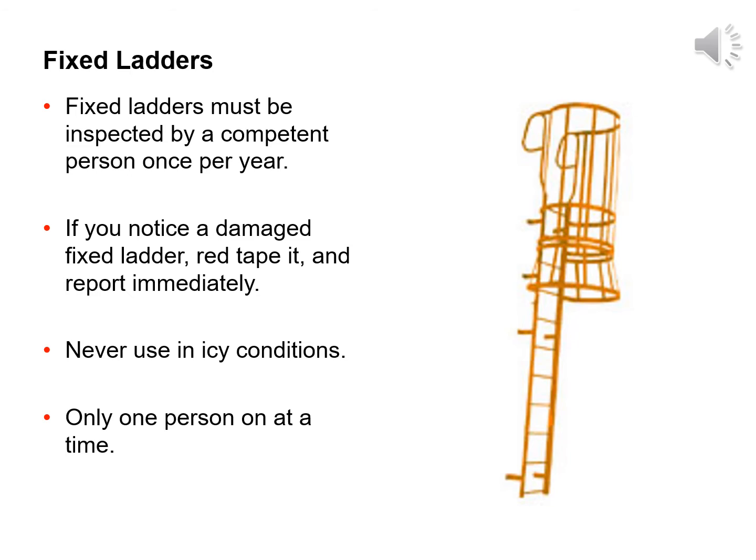Only one person at a time is permitted on a fixed ladder unless the ladder is specifically designed for more than one climber. Never jump or slide down from the ladder or climb more than one rung at a time.